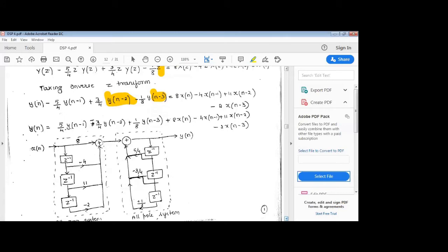And this is the important step here, the plotting of your transfer function. How to plot this particular transfer function in the form of a direct form one structure? I am trying to relate the transfer function, that is the expression, with two terms. One is the output, y of n, and the input is x of n. That is, first write down one complete straight line. I'm just trying to rewrite it in terms of steps.